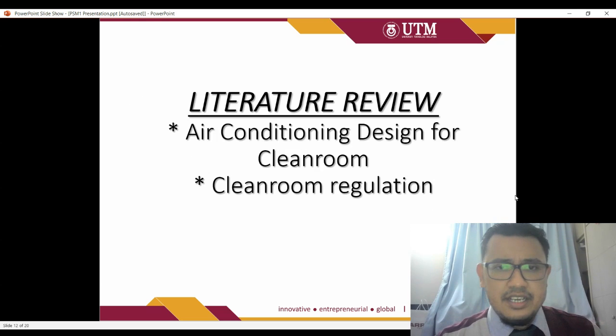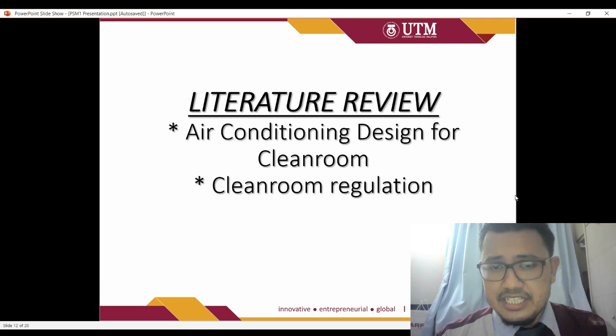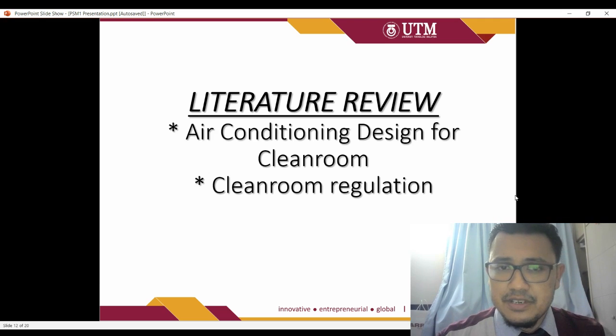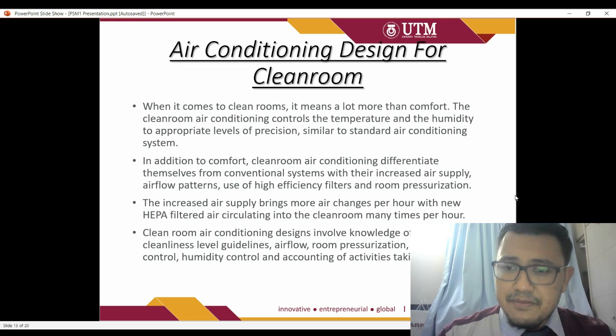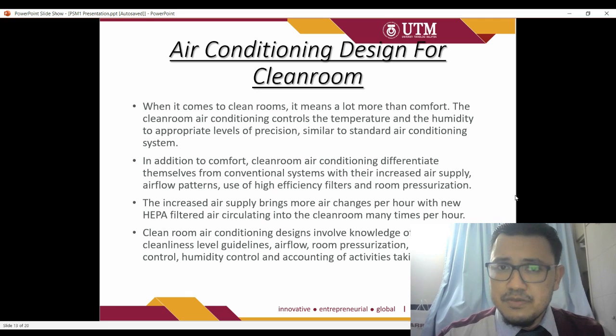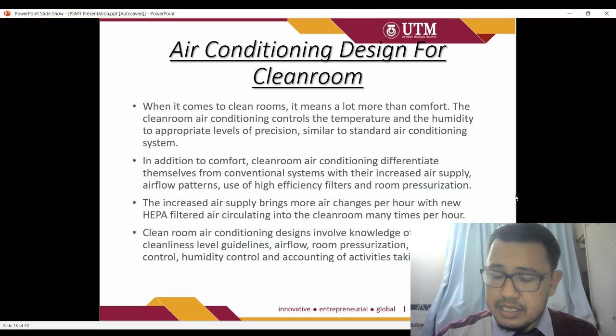Then the next topic is the literature review, which covers the basic air conditioning system for the clean room and the clean room regulation. So the air conditioning design for a clean room is more than comfort. It is control of the environment. The clean room controls the temperature and the RH, the humidity, to an appropriate level of precision, some plus minus 0.5 for temperature, and maybe 5% for the RH.